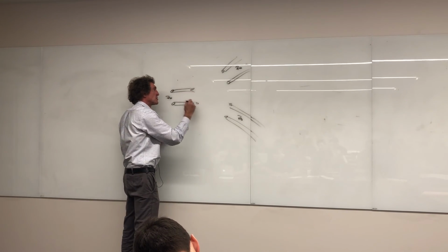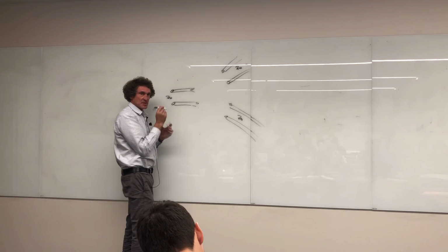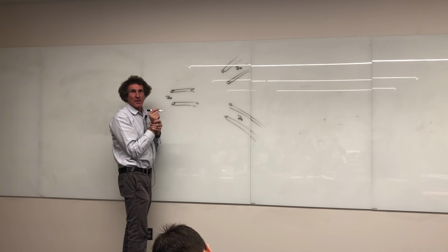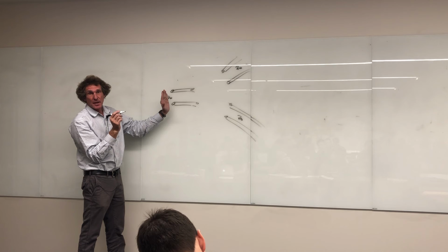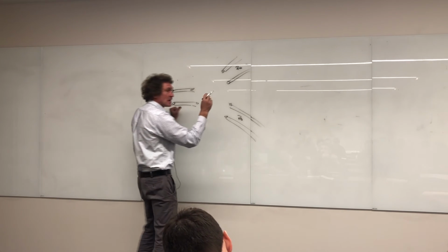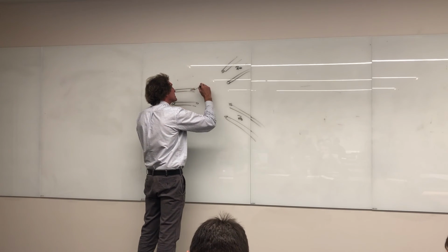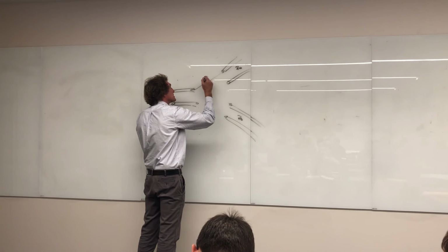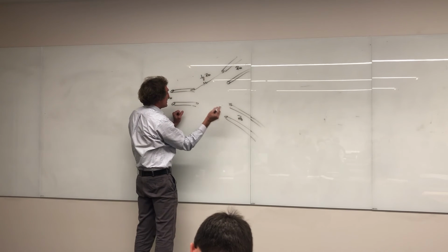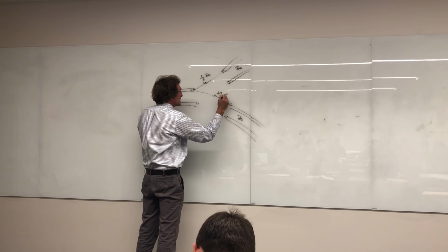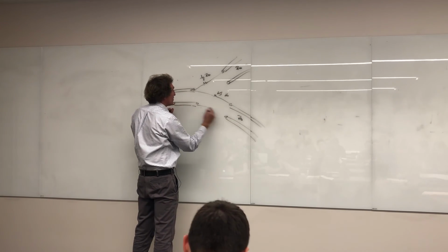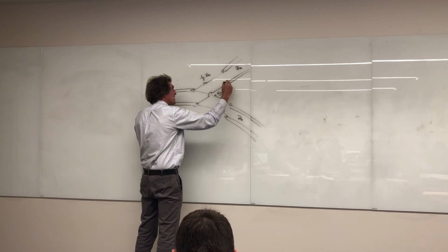I'm literally showing you in terms of these are 2 wires separating so you can see what goes on. What they want to make sure is this happens: the impedance looking into all these things looks the same. Follow me? So what they're going to do is they're going to put a simple resistor here, and the resistor is going to have a value of 1/3 Z0 here. Then they're going to put a resistor here of 1/3 Z0. Now, bear with me. This is not a good drawing, but you've all followed me.